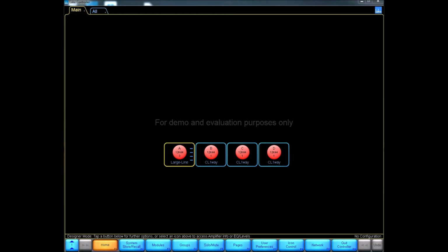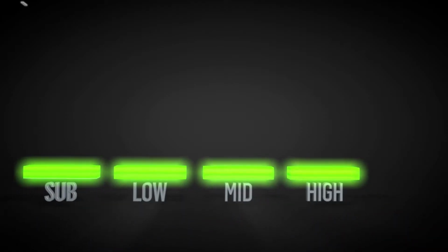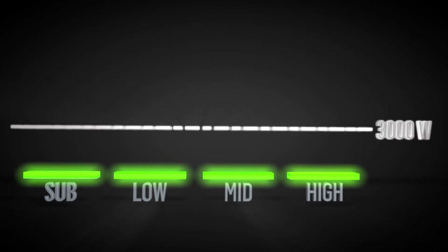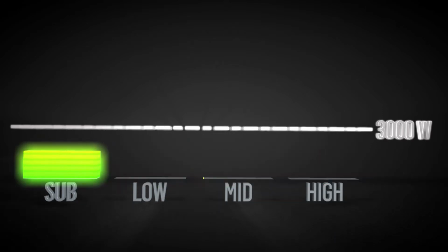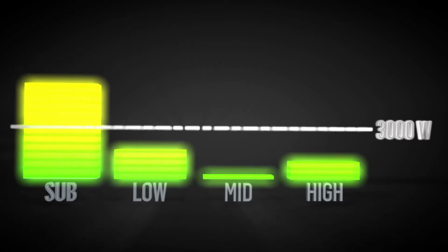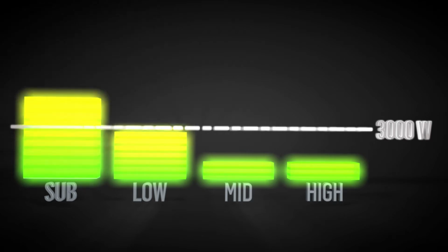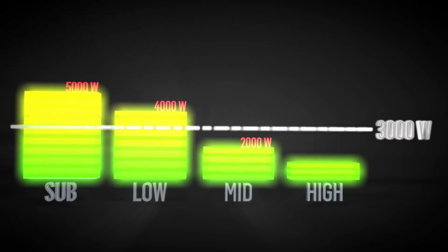The Rational Power Management feature was launched together with PLM Plus and D-series amplifiers. RPM allows for flexible allocation of power across the different channels. The way it works is that any power output of a PLM or D-series amplifier can deliver a total of 5,900 watts. If running power-hungry speakers on one channel while driving another channel with less demands, you can allocate more power to the more power-hungry channel.